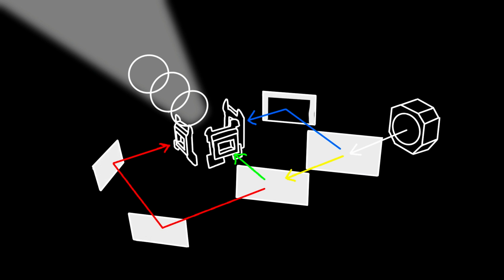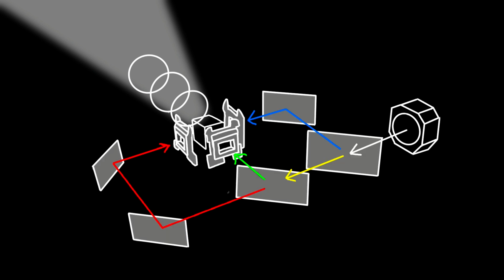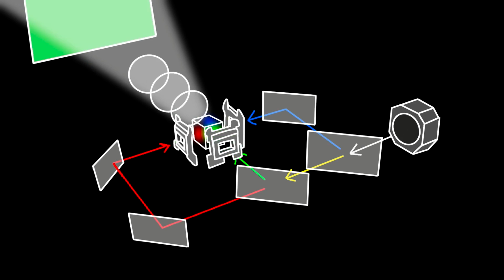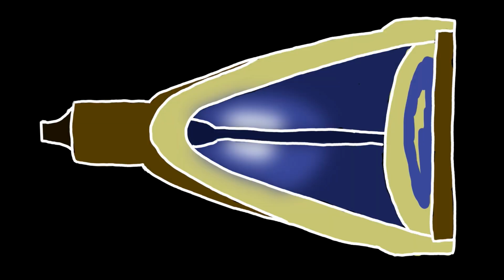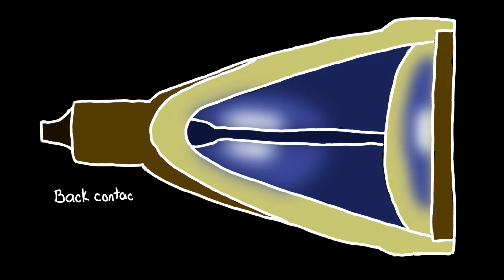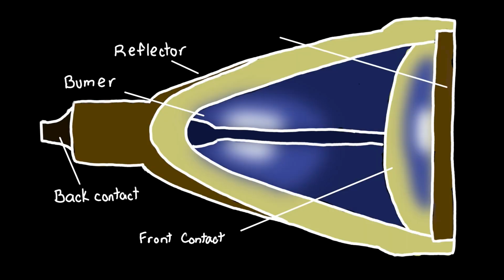A projector is an optical device that receives a video signal and projects the corresponding image on a projection screen using a lens. They can also be used to project on different surfaces and create several unique experiences using the content provided. Every projector has a light source that creates white light and is focused through a light path or light pipe. From there, the white light is separated by a series of dichroic mirrors or a beam-splitting prism where the individual colors are processed, combined, and projected through its lens.